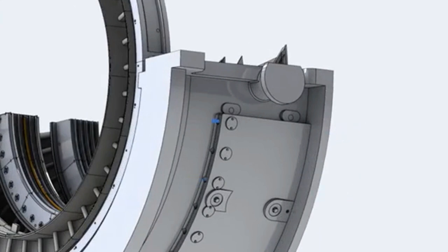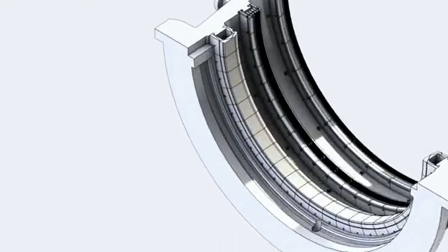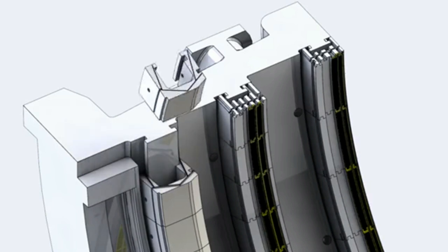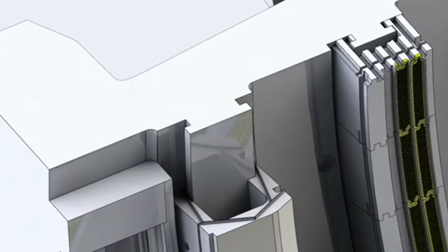Unlike the compressor blades, the turbine rotating bucket tips don't run directly against the stator casing, but against curved segments called the shrouds. The primary function of the shroud is to minimize the tip leakage. These shrouds are attached to the turbine shell by sliding onto the T-hook arrangement machined on the turbine shell.